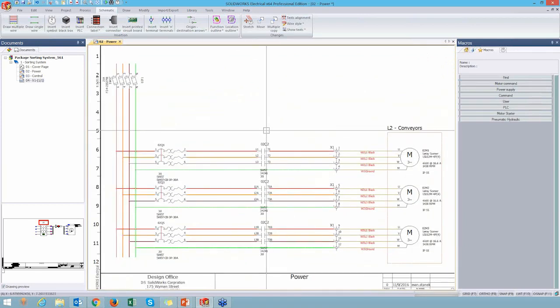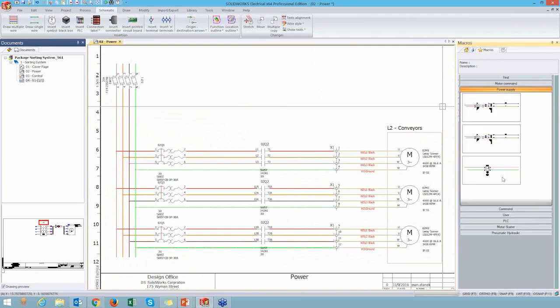So final steps on this part of the schematic will be, we basically just need to make a power supply that will be sending our 24-volt control signal over to page 3, where our controls will be. So in this case, we could go ahead, draw wires, put in a power supply, etc. We'll make it simple, and I'll demonstrate how these macros work.